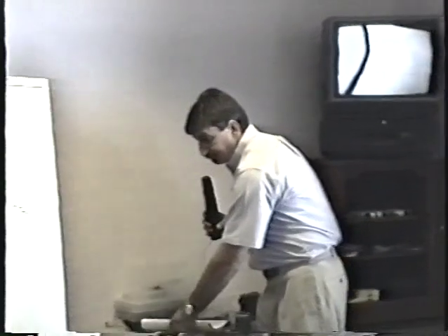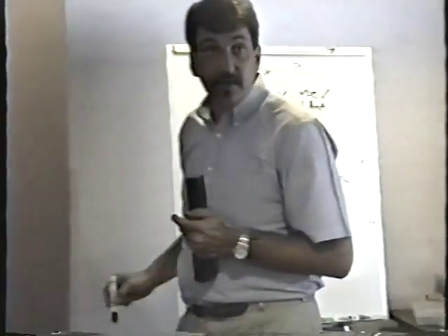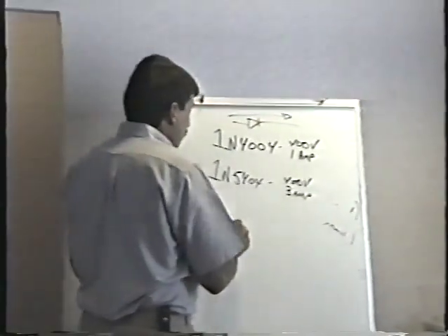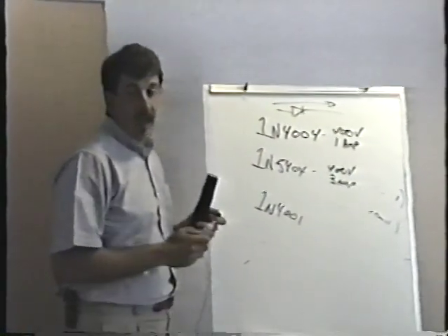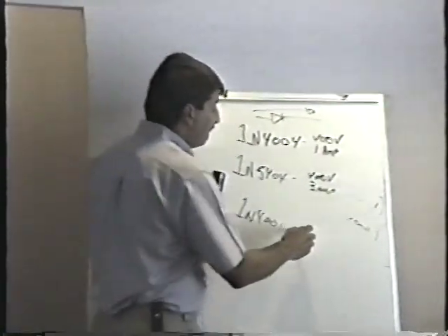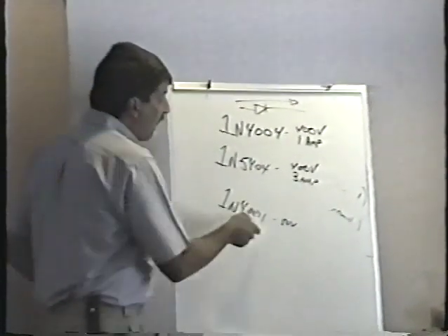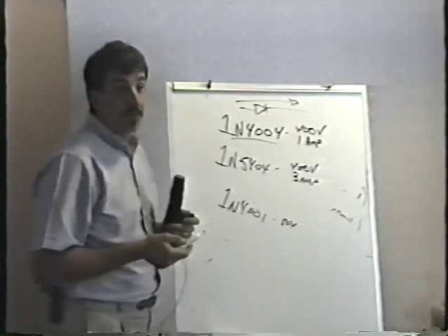For example, another common diode that you might see in many different places is a 1N4001. What's the voltage rating of that guy? That's only a 50 volt diode, isn't it? If I have a 1N4001 and it's bad, I can use a 1N4004 as a substitution.